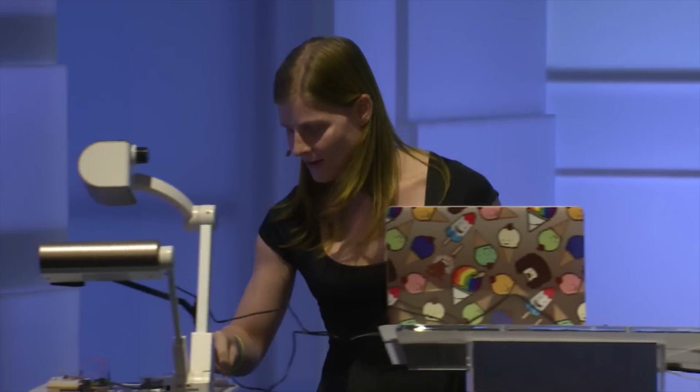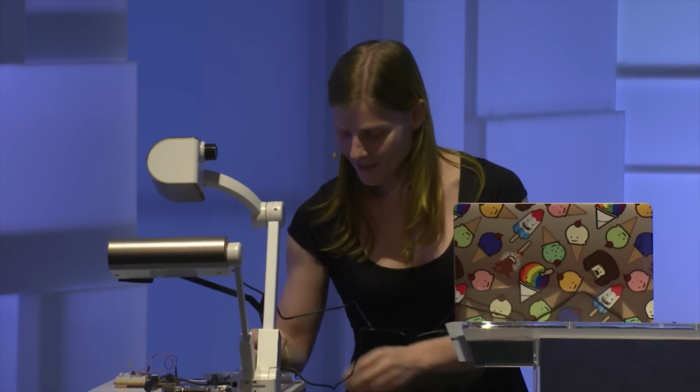Oh, so the question was, why did the LED not get angry because I put 5 volts across the LED, and I kind of did a trick. Because LEDs come in different colors, and it's one of the nasty complexities, different colors, whether it be yellow or red or blue or green, have different ranges of voltages they're willing to accept. And one pitfall, just to prevent your first fire incident, is a 5-volt Arduino Uno and a red LED do not get along like that. The red one will light up briefly, and then it will never light up again. That's because the maximum voltage is less than 5.